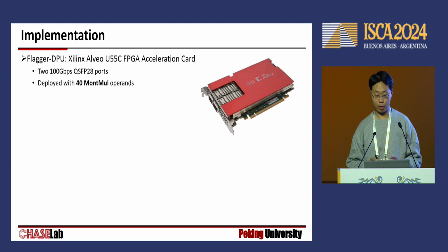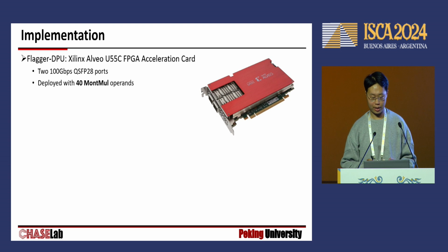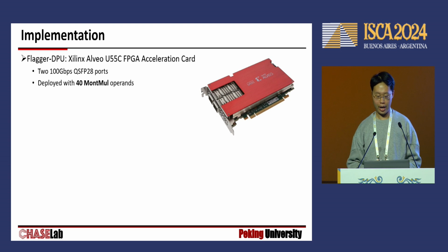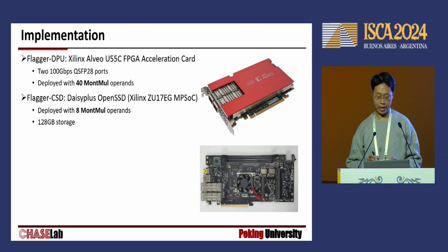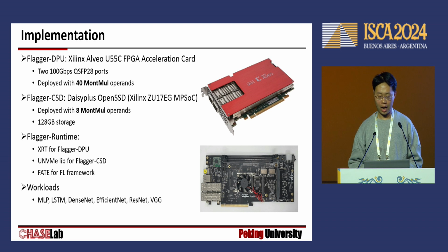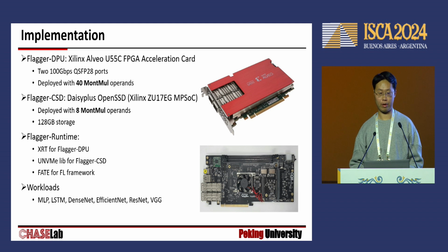We implemented and deployed Flagger in a real system. We leveraged the Xilinx Alveo FPGA accelerator card for Flagger DPU and deployed 40 modular multiplication operands. For the Flagger CSD, we leveraged the Daisy Plus OpenSSD and it deployed 8 operands. The Flagger runtime is constructed from the Xilinx runtime, the UNVMe library, and the FATE framework. We also chose multiple widely used machine learning models to verify Flagger.